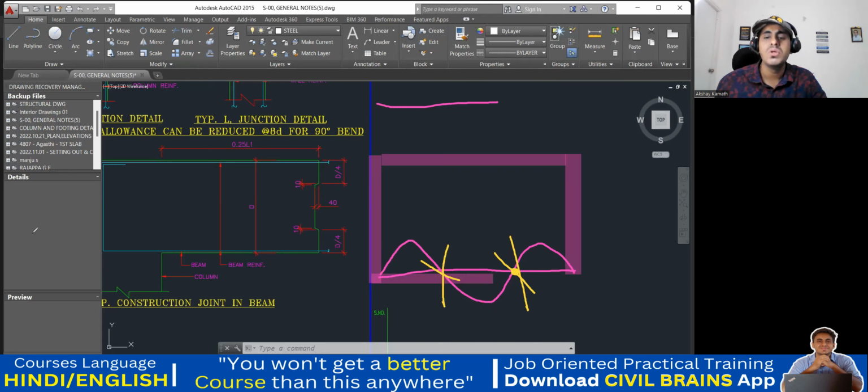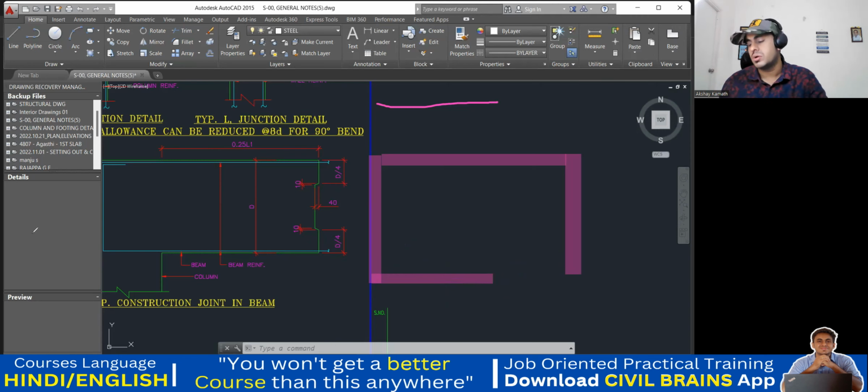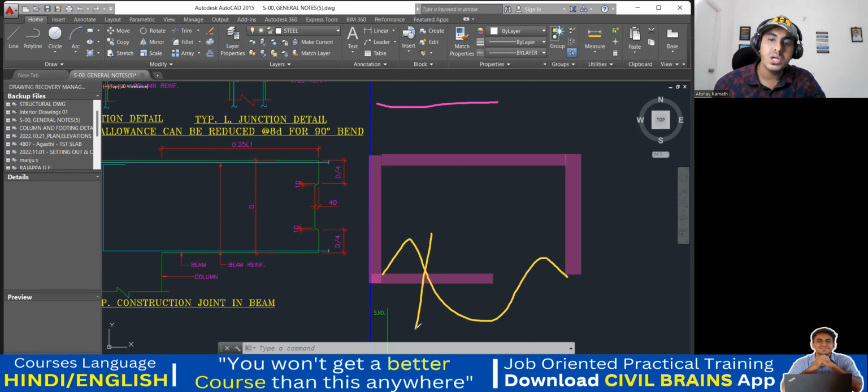Or let us say rain did not come. Today you started with concreting, and by 6 o'clock in the evening, all the laborers got tired, and also the electricity went off. You tried everything, but you couldn't bring the electricity, and you couldn't continue your concreting. And you said tomorrow I'll start the concreting. So when you know that tomorrow you're going to start, then what do you do? At least today you finish your beam concreting up to which point exactly? Either you could have stopped it here, but you didn't know that. No problem. At least this much portion you do.